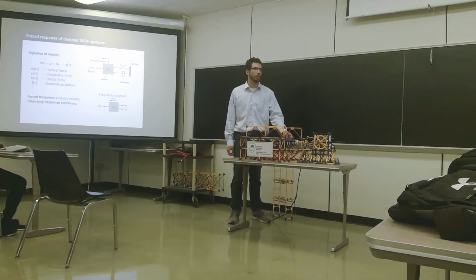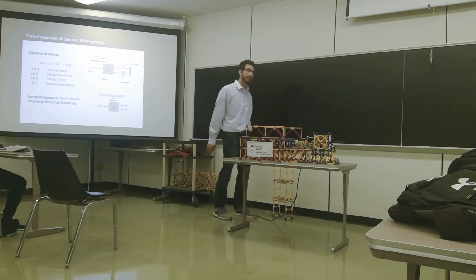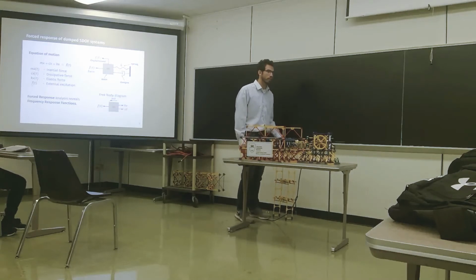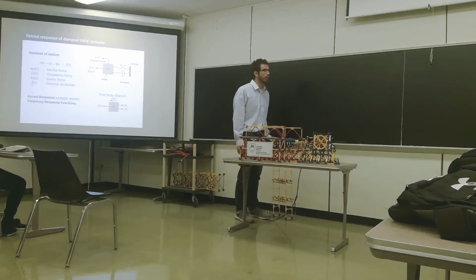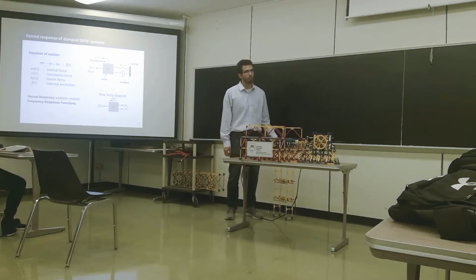Even after the initial set? Right, months and years. I believe the concrete in the Hoover Dam is still curing, in the center of it. Does it increase stiffness as it cures? I believe so, yes, it does, because the concrete's elastic modulus is proportional to the square root of its compressive strength. So do you have to take that into consideration with buildings? Like you said, the damage would decrease the natural frequency over time, but would the natural frequency also increase?